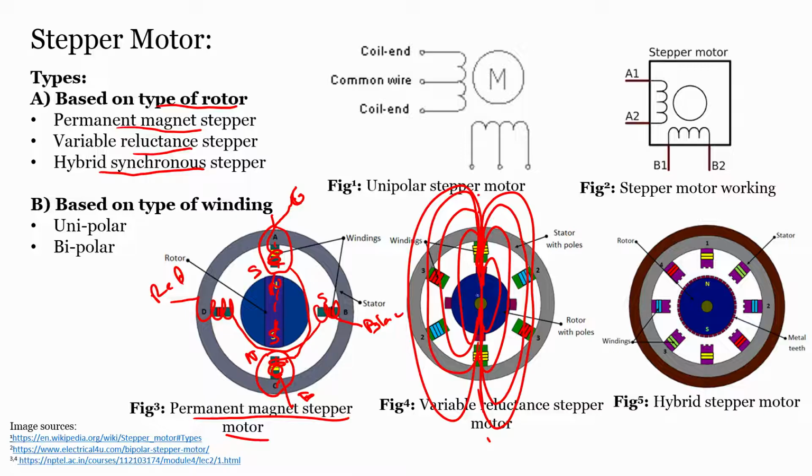this rotor shaft over here will act such that it will always try to reduce the resistance, or reluctance, in the path. The magnetic field has to pass through this soft iron material and go through this coil and complete the loop, since magnetic fields are closed loops. So, it will always try to reduce the reluctance.